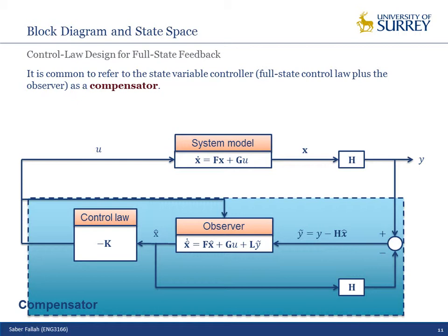To be honest, for your coursework, you can use PID to design the suspension because you need to make many simplifications in solving the system. For practice it is good, but in reality it's not good. Because for the suspension you have a multi-objective system. You want to reduce many things: suspension deflection, suspension velocity, and suspension acceleration. Using PID you can't do this optimization, but using the state space, you can.